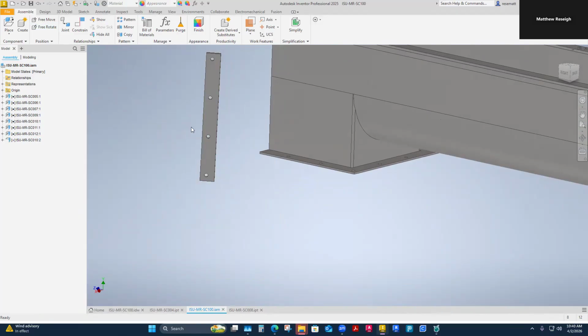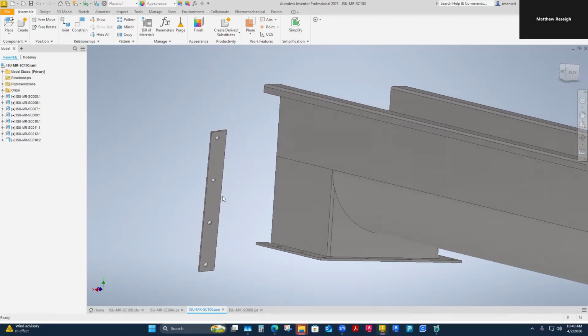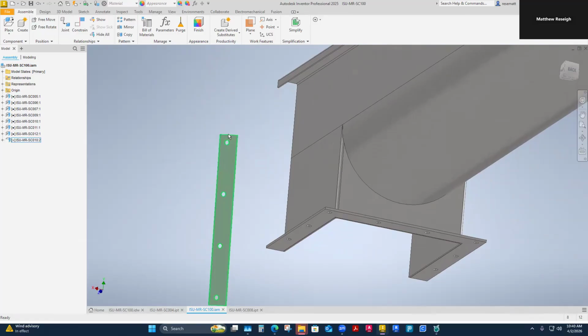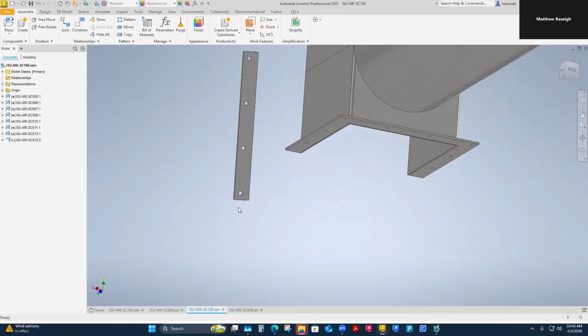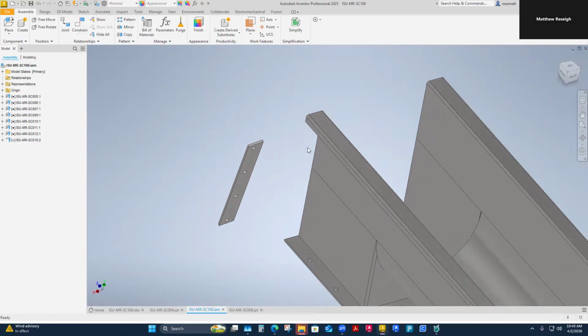F7 to slice graphics. Hit keyboard G and then select it, and it brings up that little telescope here. And then I can just rotate these parts into how I might need them. And then I've got to do some constraints. All I did is I needed to rotate that around. I didn't want to flip it upside down. I think we're pretty well symmetrical from where the whole pattern is from the ends, but I definitely want to keep it like top is top.